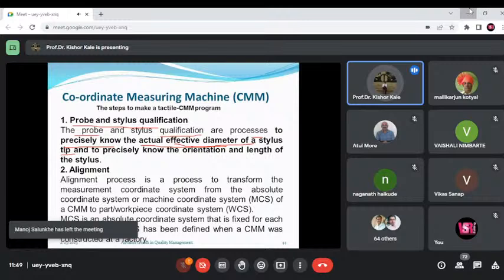But if we align it like this, the distance between the corresponding point A and the corresponding point B is actually 2.48. The method measures the minimum distance, which is only 1.80, but the corresponding distance is 2.48. So this will be accepted, although it is actually outside the tolerance zone and should be rejected. That is the problem with the scanners.